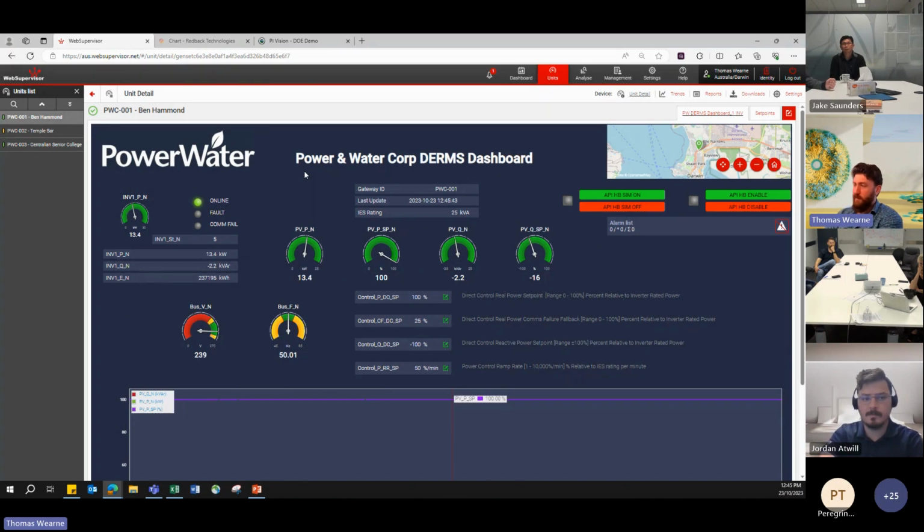We could probably specify that the droop curve I showed previously should only operate when we're sitting between 220 and 245 volts or something like that. Some value where we're not going to get into the situation of injecting power, raising the voltage, and causing other PV units to trip, for example. So you've just got to develop all of that logic and build it into how it operates.